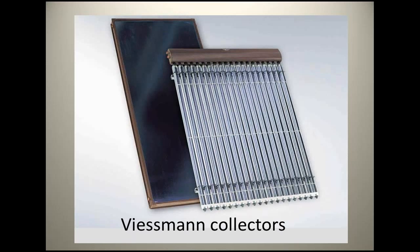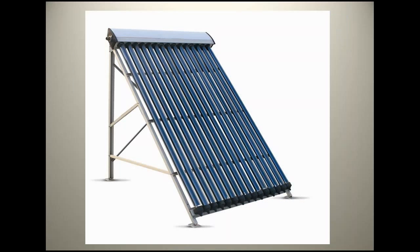We'll go in and talk a little bit more about those collectors. Here's another one. There's a nice rack here. Here's the header. The water goes in one side, goes in the outside. It doesn't go down here. And these are put at a steep angle, because these evacuated tubes are really good at keeping heat in, so snow doesn't melt off and you get snow packed around them. So it's important to keep them at a pretty good angle. But if we get winters like this one, we don't have this snow.